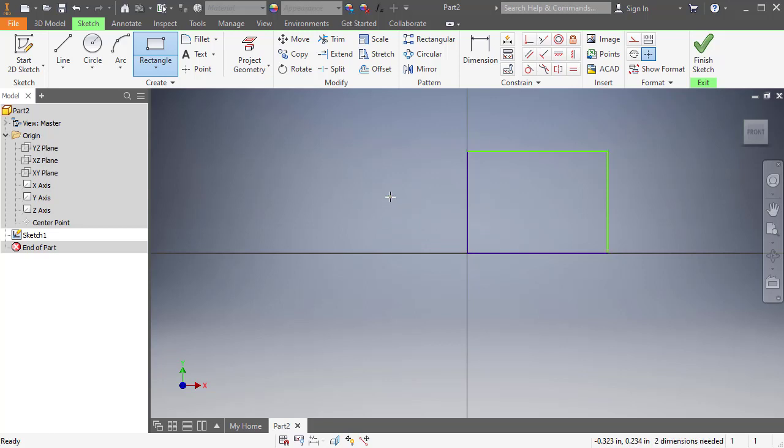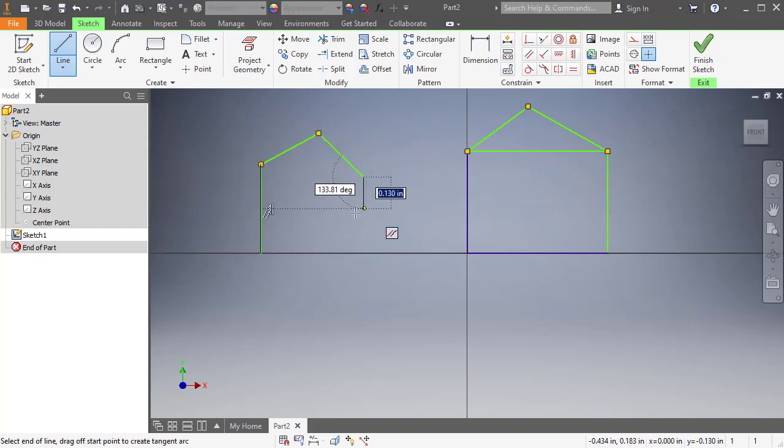Now, I do want to cover a couple of the other tools. So that was the rectangle. We also have a line. So if we click on here, and let's say we wanted to add something on the top here, I'm going to click and release, click and release, click and release, and I make a line now here. And I'm going to make another one over here. So as I click and release here, it's going to continue to make this until I close this object up, and then it's going to complete it, and it's going to stop making a line.